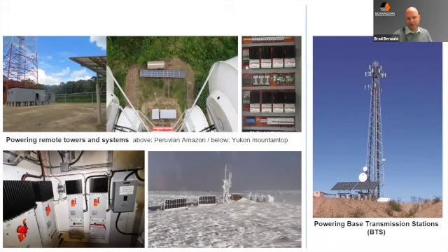In the bottom left, you can see an example where these were 600 volt charge controllers with an array that was actually located quite far from the system. It's hard to see the scale there, but that's actually a telecom shelter building with a pretty substantial antenna. Those 600 volt controllers, 4 of them, are handling about 12 kilowatts of power. And there are several hundred feet between the solar runs, the PV wiring runs, and they had to run it for high voltage.